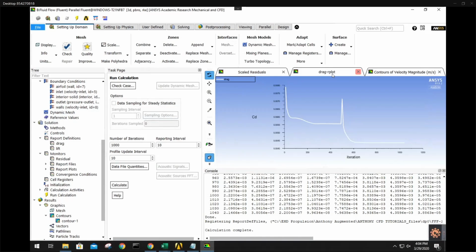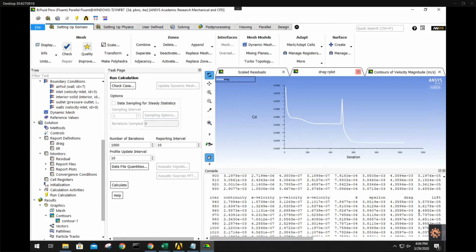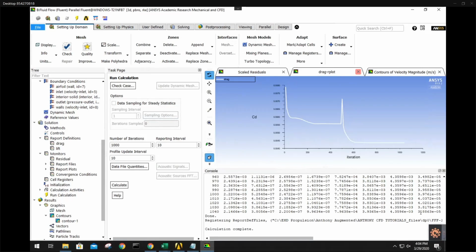And that shows you the effects of wall effects. So if I had it much farther away, those walls would not have had an effect on the drag. But from right now, it looks like my drag is an under prediction. I don't know why. My lift is pretty good, basically 0.